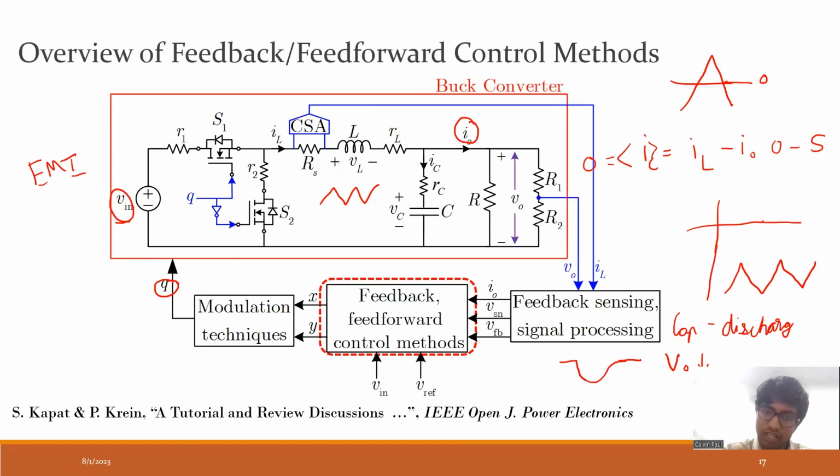So we have to use a modulation and control technique to limit the EMI that would be generated. Another thing is that the inductor current cannot just go to a very large value. It should be capped off. If it goes above a certain value, it should be turned off and it should again start falling. All this can be implemented via control.